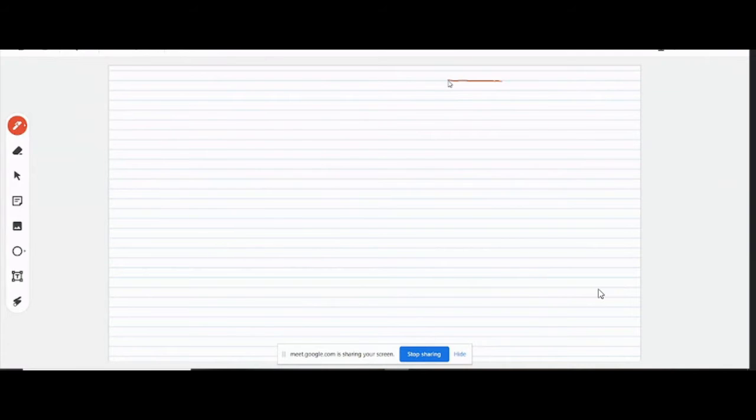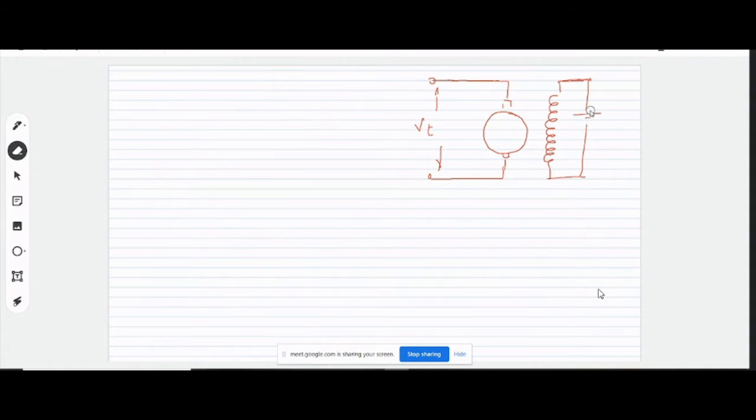I am saying that you must have noted this: suppose it is a separately excited motor, then in that case even if we alter the terminal voltage, your field flux will not be affected by this, right? It may remain constant, unless we do something over here to change this field flux, right? So this could be kept constant.